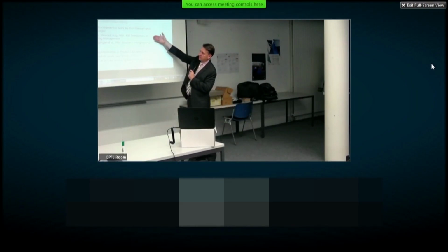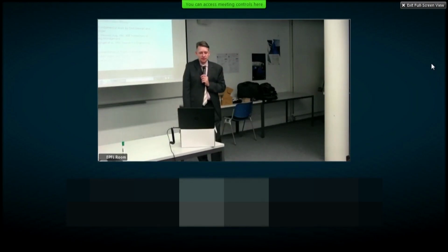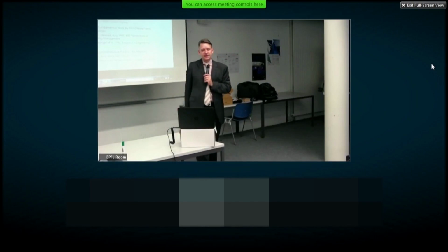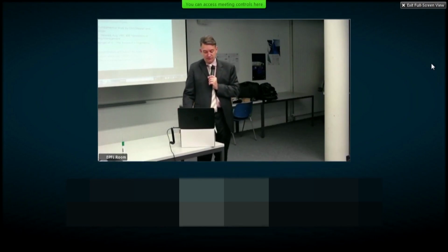So a lot of work was done originally by Don Stewart on this. This is an original reference from '81. And then at MIT, Professor Steve Eppinger at the Sloan School has done a lot of work on DSMs. So fundamentally, it's a matrix representation of your product architecture. Most of the literature you find just uses the simplest, this binary DSM. But I'm actually a fan of adding information into the DSM that tells you about the physics of the interface as well.